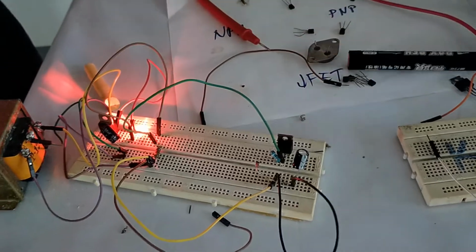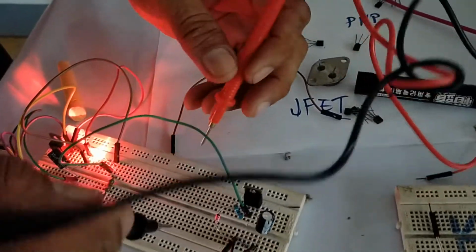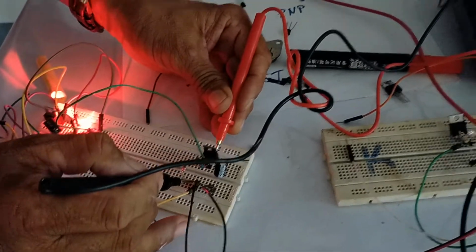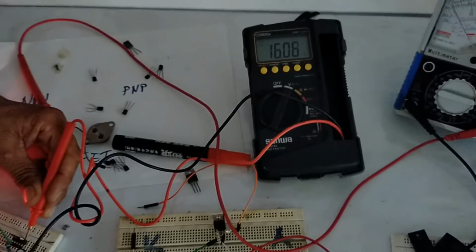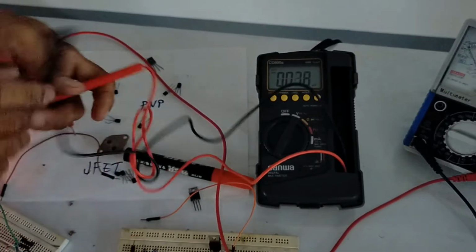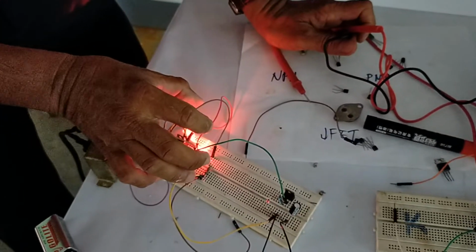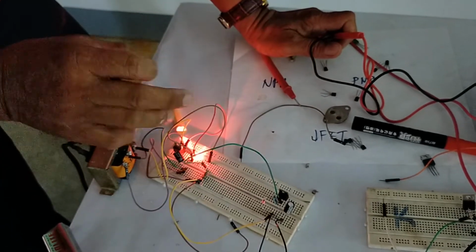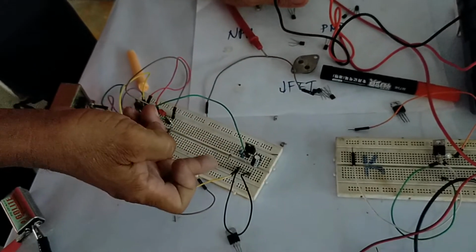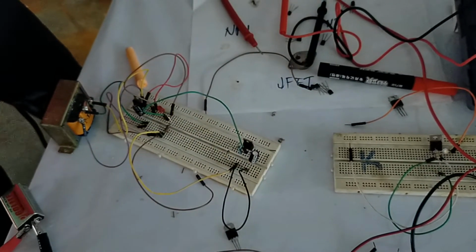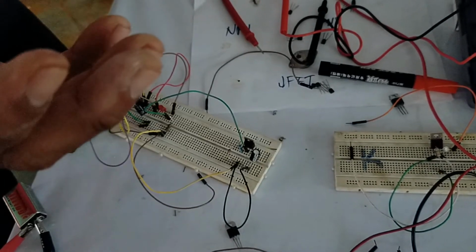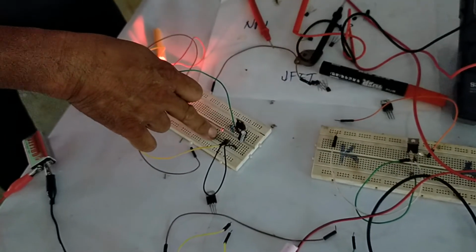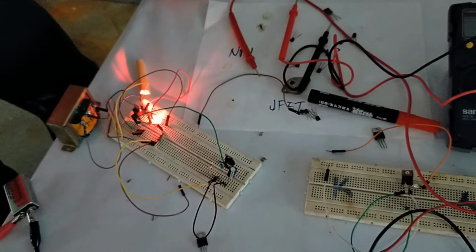If we measure the voltage here, between the collector and the ground, it is 16 volts. We have here 16 volts provided by the power supply circuit at the output of the filter capacitor. The filter capacitor provides the peak value. That is the peak value. But once it enters the regulator circuit, because the regulator circuit will always provide a constant output voltage based on the Zener diode, the voltage outputted is around 11 point something.